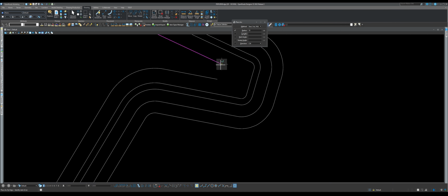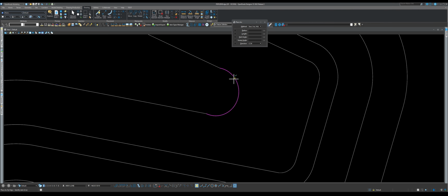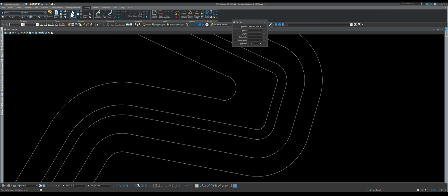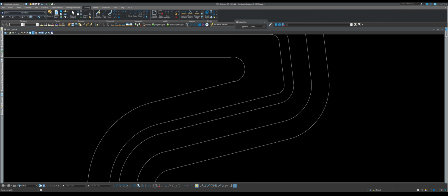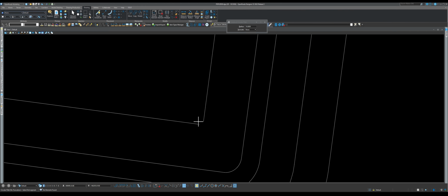Okay, let's do a 10 here. So I want to start from here, and I want to start from here, and I want my 10 to be here. Yeah, but as you can see, it's not tangent. Ugh. Let me do it like this. Like I said, it's not tangent because I'm using the wrong one. So let's do this. And I just remembered I could have used the other tool here. Where is it? Y'all can tell, which is constant circular fillet, because I don't use these as much. Okay, so make this 10, and then click on this one, and click on this one, and we got this one. So here we want 5, right? So let's make a 5 here.